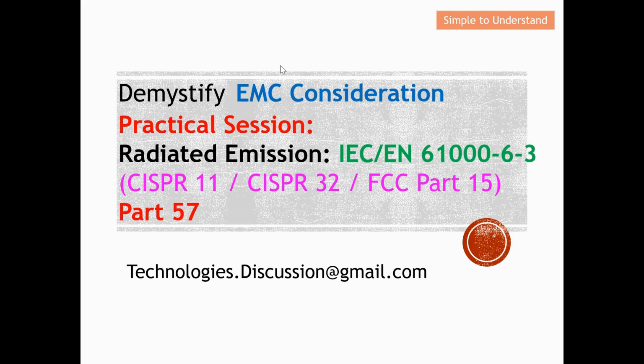Today, I'd like to continue the discussion on EMC consideration. For this video, I'm going to discuss the practical aspect of radiated emission, also known as RE. I'm going to do a demo on how we can execute this radiated emission test based on the IEC EN 61000-6-3 standard, also known as CISPR 11. For this video, I'm testing the DUT against the CISPR 11 standard.